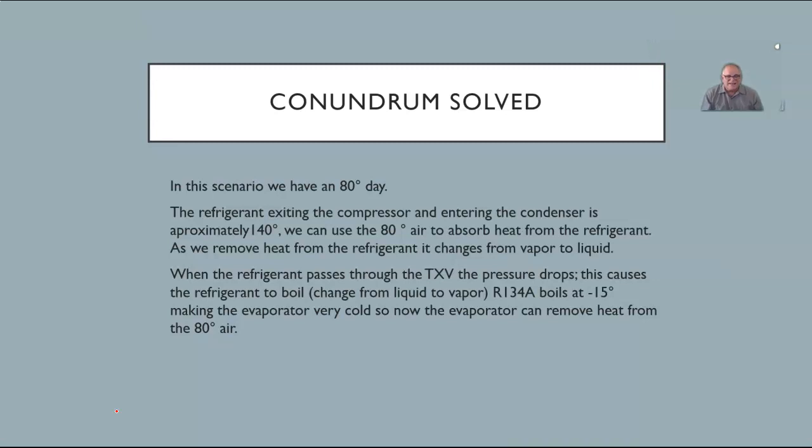So that is the nature of the refrigerant: the pressure that it's at when the system is charged the way it's supposed to be. If you look at the pressure, there's a pressure temperature chart that you can use to tell what the temperature of the refrigerant is by what the pressure is.